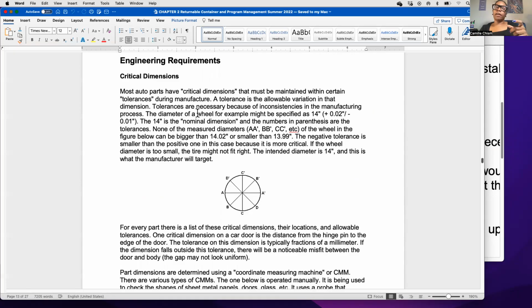But if you find out that this part is on the high end of the tolerance and you try to put 12 in that same bin, now maybe you can only get 10. And you may not understand why. Well, what? This fit before. This is what I was told. But you have to also look at the tolerances and understand what the tolerances are for the part. And that variation is normal because nothing is 100% precise. There will be variance in everything.